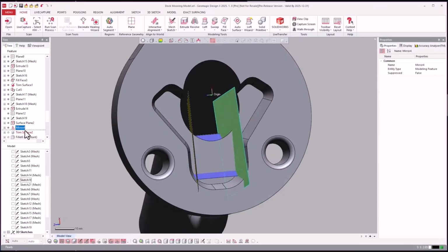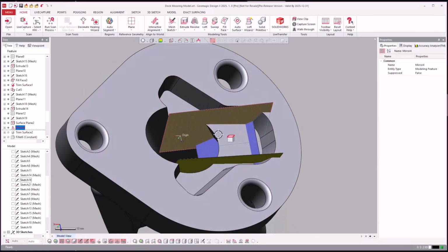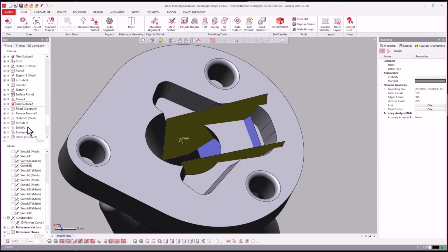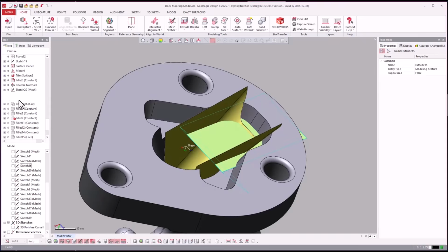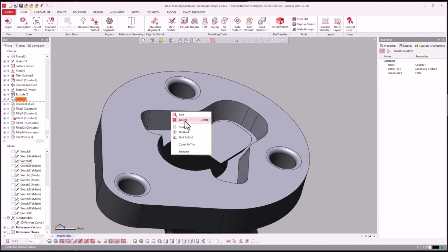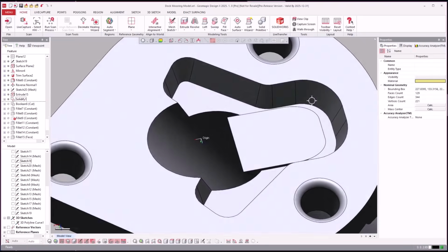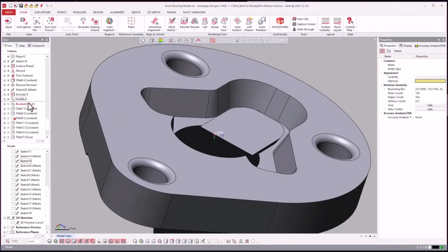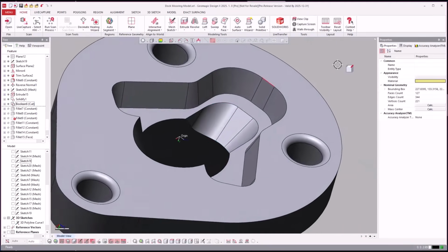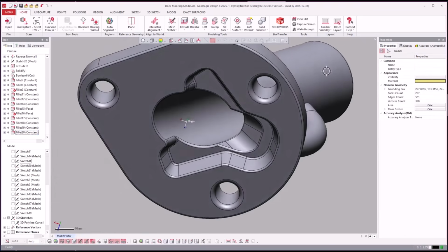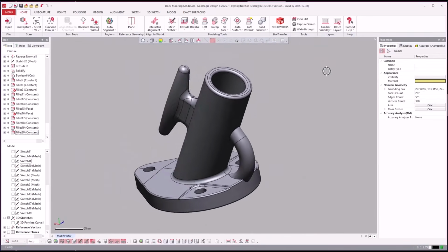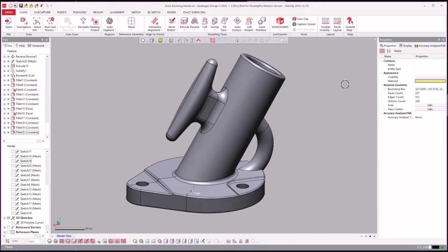And then let's see where we go with this here. Oh, there's another little cutout there. So trim these together. Trim that. Oh, we used the solidify command, which is awesome. So they created a solid based on surfaces that enclose a shape, and then boolean that away there from that. And then the rest are just fillets, filleting the entire thing to death there. So now, and then you fillet the whole thing. So there we have the final modeling process.